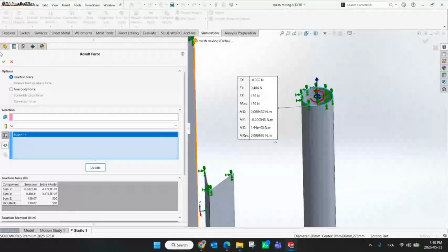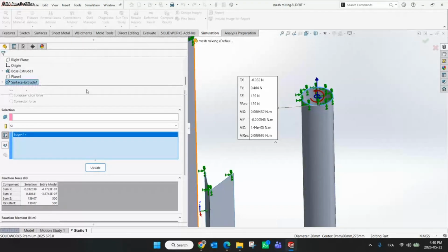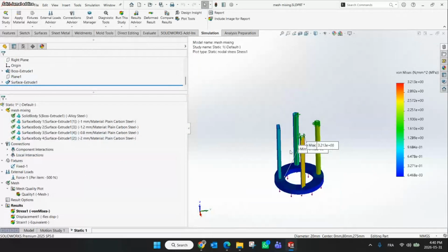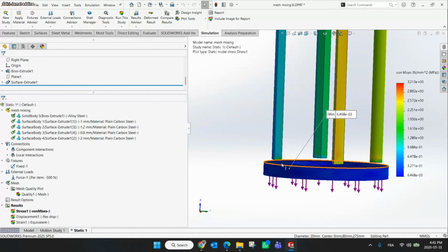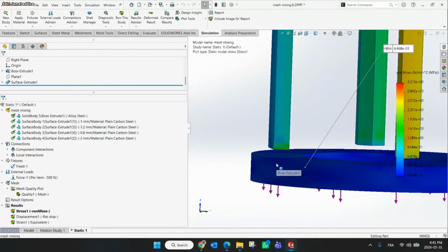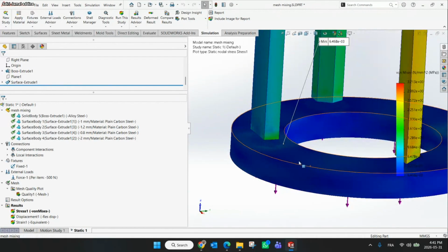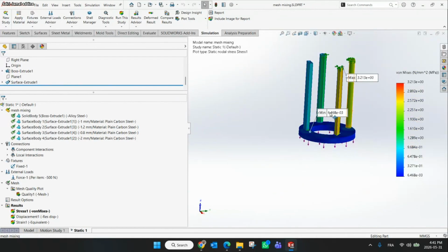This depends on the exam you are going to get, because as I said, there are several parts, and each one is going to get a specific part for its own exam. But this is the common example you are going to get in the exam, and one of the trickiest ones that people mostly fail, because they always forget to set the bonded position between the bottom edges and the top face of the solid body, which leads to errors and bad results.